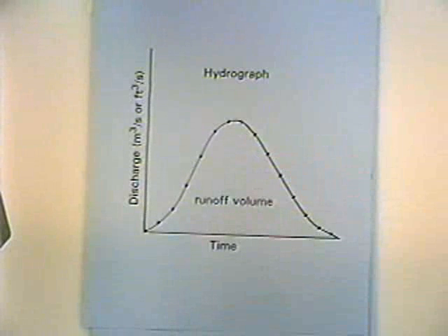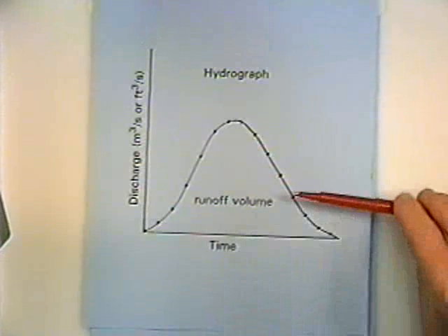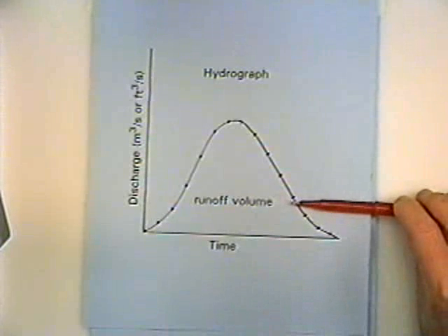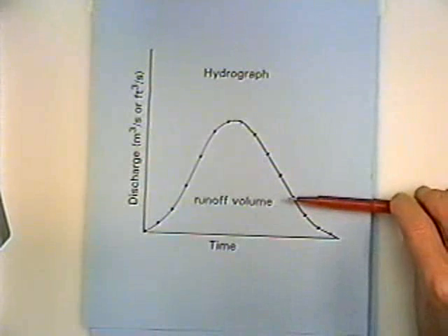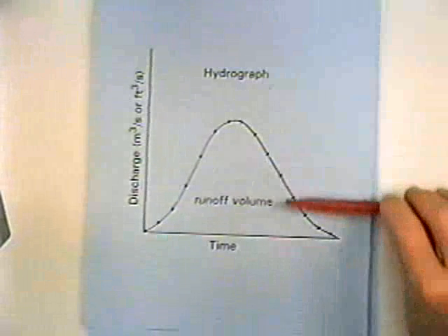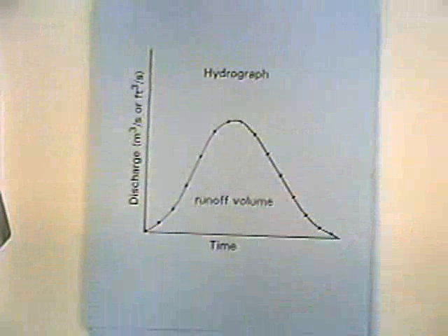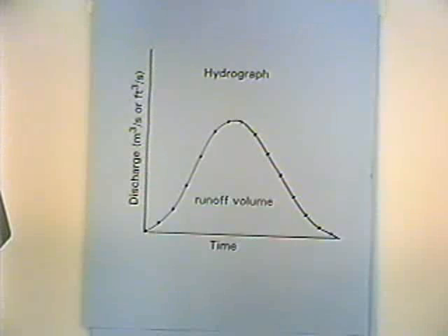Let's say that we have a rainfall event. In the previous example, we had 10.4 inches of rainfall, and that gave us a runoff volume of 8.7 inches. So the concept of the unit hydrograph is that all you would have to do is take a unit hydrograph and multiply it by 8.7 inches to get the runoff hydrograph that corresponds to an 8.7 inch direct runoff volume rainfall event.